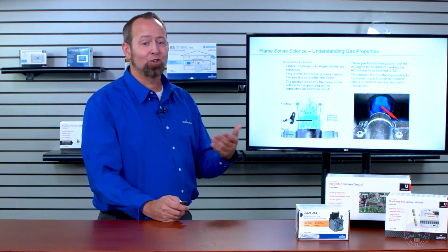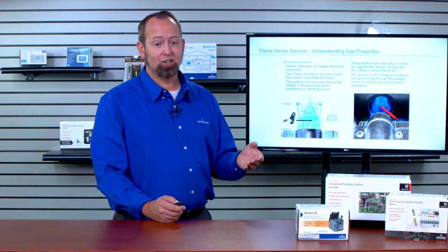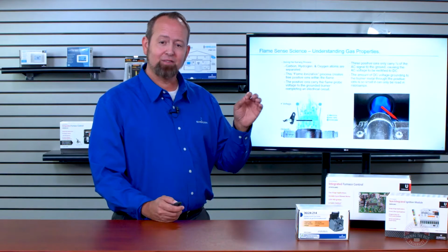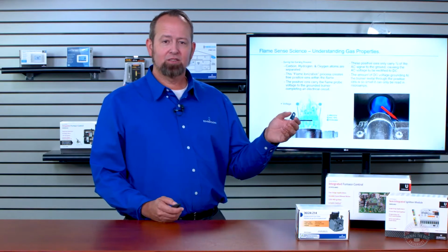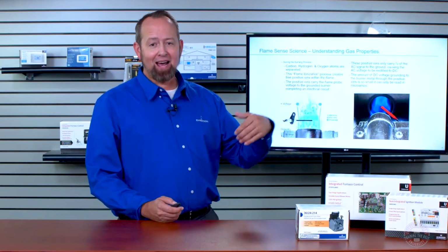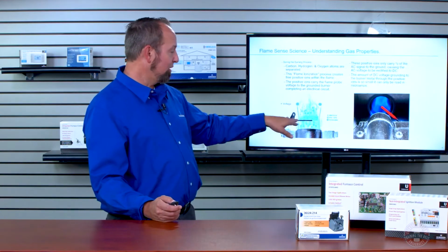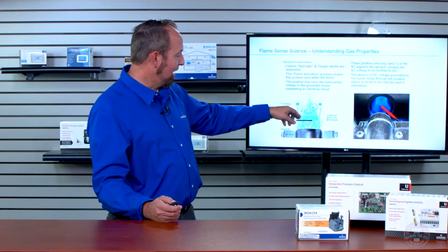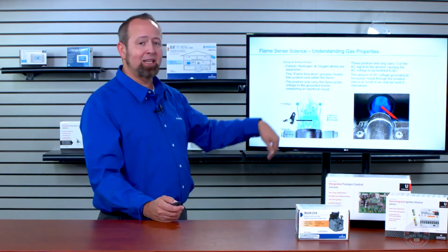You want to make sure that you're aware that the electric is there, and it's something that you're not intentionally reaching in and touching and getting a hold of. But the reason that the current is so small is it's carrying this micro amperage, this very low current signal, back through that wire back to the control board. And how it reads that, how it knows that there's resistance there, is the voltage that's on the rod is actually continuing through those positive ions to the burner ground, and it's completing the circuit.